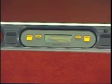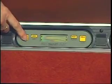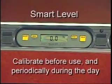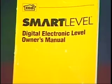Third is the SMART level. The most important thing to remember about the SMART level is that it is a sensitive measuring device and it needs to be calibrated before use as well as periodically during the day for the most accurate measurements. This is especially true if the level is dropped or jostled while in use. Always refer to the instructions that came with your SMART level for the proper calibration method.